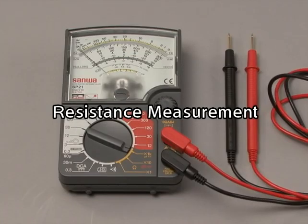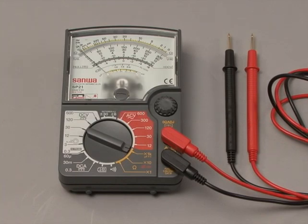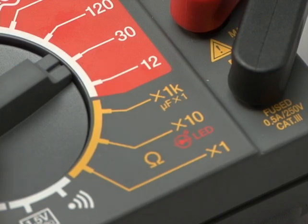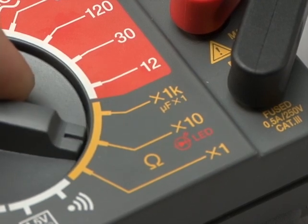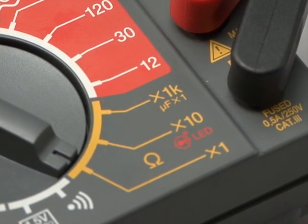In the resistance thermometer, the resistance value changes according to changes in the measured temperature. The resistance value is measured by using a tester to check whether the resistance thermometer is normal or disconnected. Set the rotary switch to measurement of resistance, ohms. When the resistance value to be measured is not known, set the measurement range to minimum.